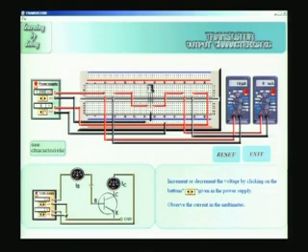Now, what I am going to do is, I am going to vary the VCC supply, which is at the bottom, continuously in steps of, let us say, 0.5, and see what happens to the collector current. I am going to keep the IB, the base current, constant, and I am going to vary the VCC, and for every value of VCC I apply, I will measure the collector current. Now, let me increase. Now, it is 0.5 and it is now 0.1 milliampere IC. Now, it is 1 volt VCE and it is 0.5. 1.5 it is about 1 milliampere. 2 volts, now it is 1.5 milliampere. 2.5 it is about 2 milliampere. 3 it remains at 2 milliamperes.